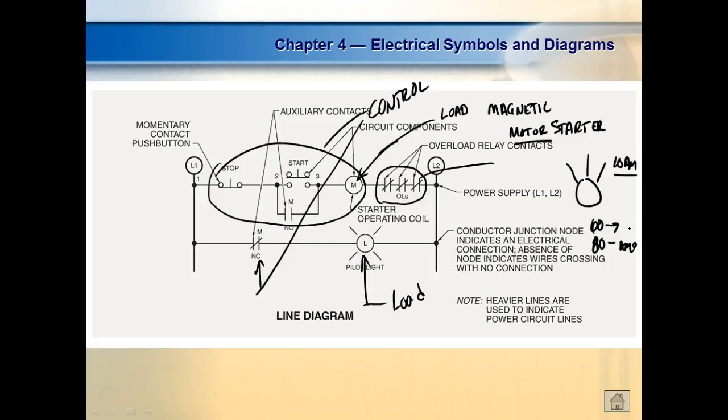So this is a magnetic motor starter. Now this is the actual relay right here. But we see something down below it. These are called overloads. What overloads do is allow overcurrent over time. That means if you pull too much current, these guys don't trip instantly. They'll let the motor start. And then if something happens, if the motor doesn't start or if the motor stalls, then over a set amount of time, this right here will kick the circuit out.